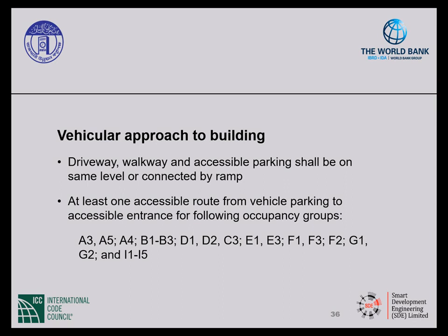So for flats, apartments, hotels, lodging, mess, boarding house, dormitory, healthcare, custodial institution for adults, educational facilities beyond secondary level, preschool facilities, offices and essential services, small shops, refueling stations, and large shops, and large and small assembly with fixed seats, large and small assembly without fixed seats, and sports facilities, at least one accessible route from a vehicle parking to accessible entrances shall be provided.